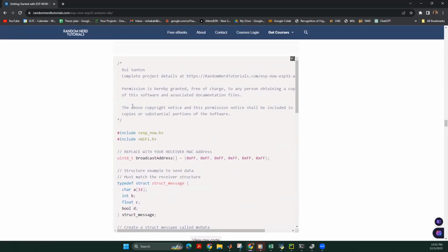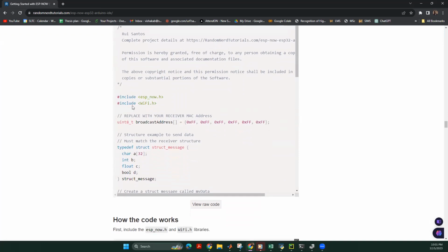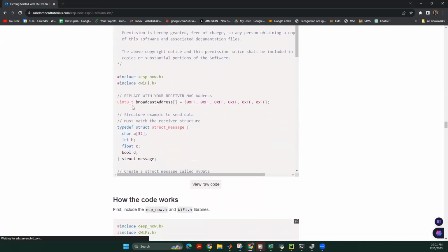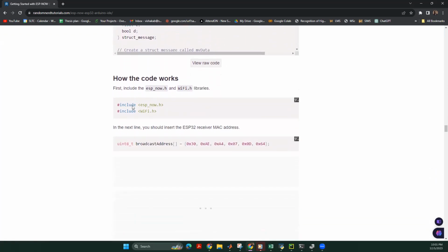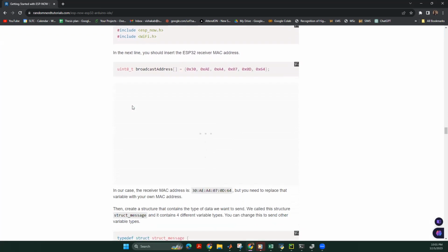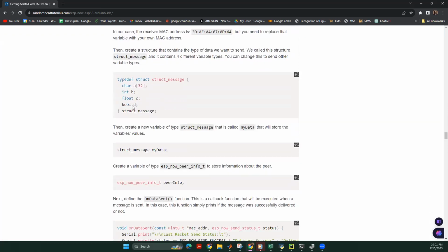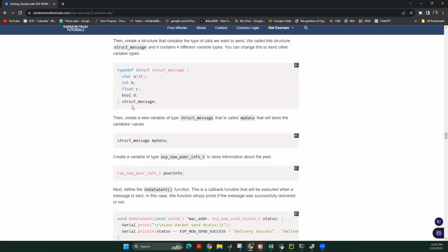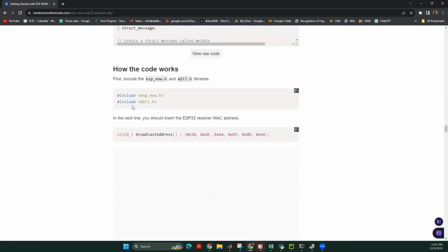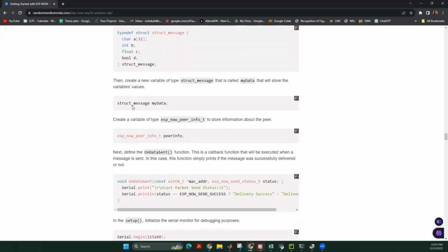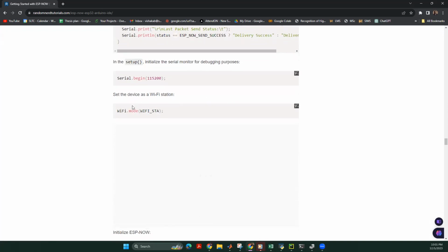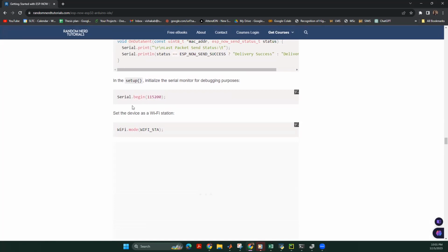What you need to do is go to the Arduino IDE, establish the ESP-NOW protocol using the defined library related to ESP-NOW, and then you can develop the algorithm in this microcontroller as given in the code. You can use this sample code. Then you can see whether you have established the Wi-Fi.